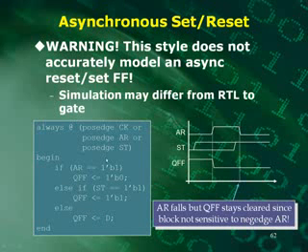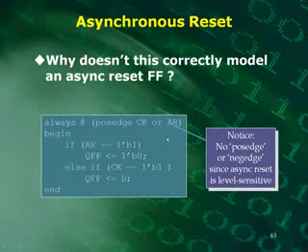So it doesn't accurately simulate it for this type of condition where you've got the set changing during the time the asynchronous reset is high. So be very careful of this.